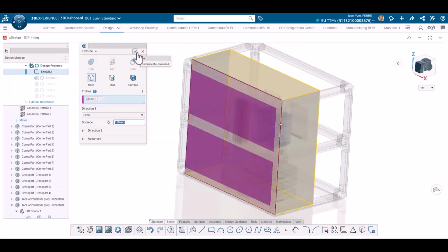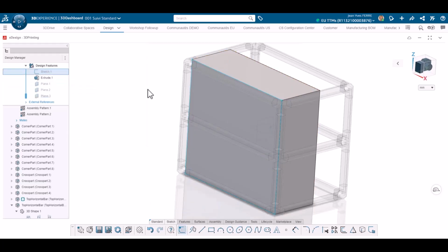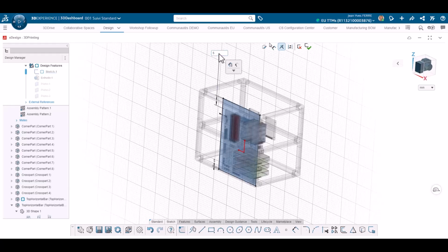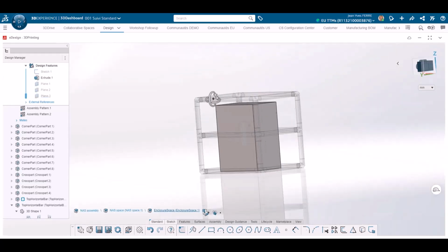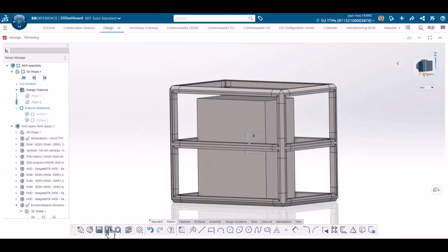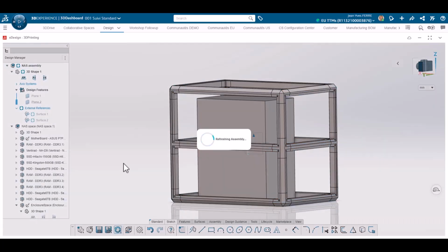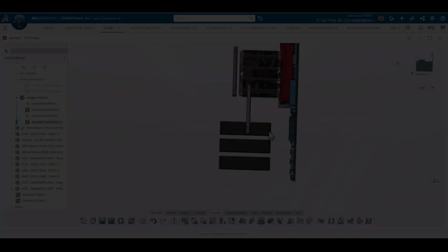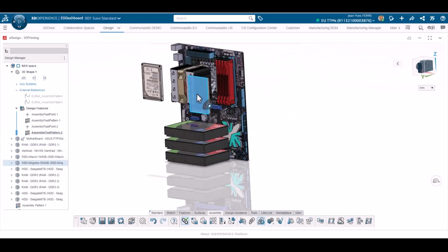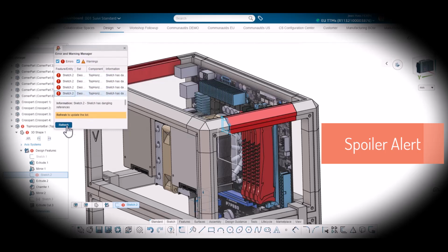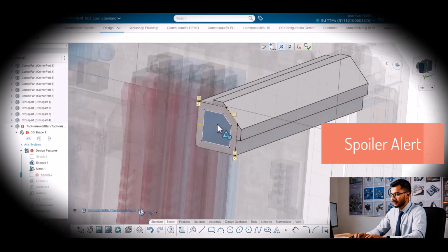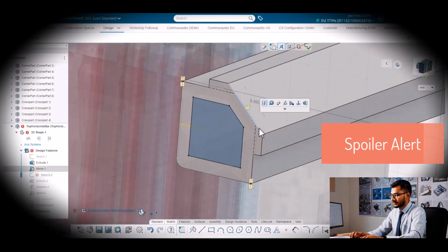Now I have built a rough layout of my components. I need to create a box around them. There will be some bars on external edges, and I would like these bars to adapt to computer component positions until I know how they are arranged inside the case. I would like xDesign to adapt bar lengths and corner positions for me. Once I decide component layout is good enough for box size and airflow, I fix bar dimensions by removing external references. Exactly what a design engineer would do in an industrial company using SOLIDWORKS xDesign.